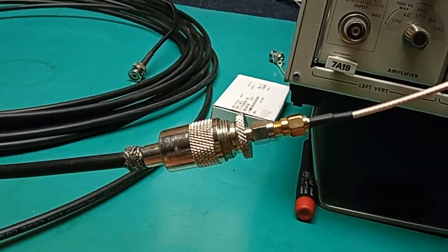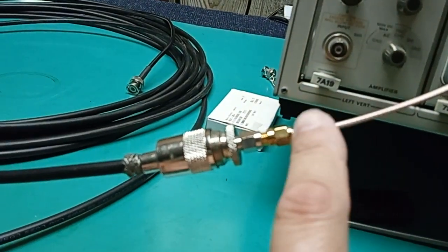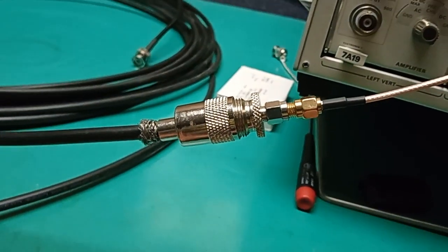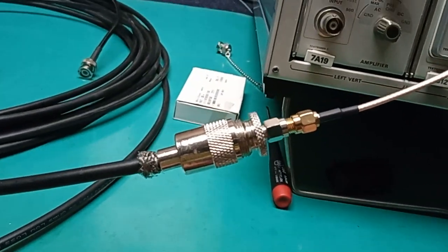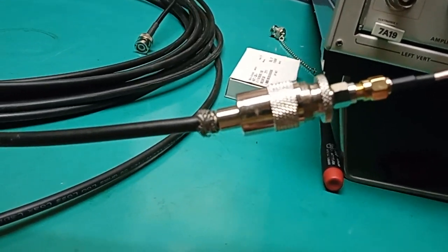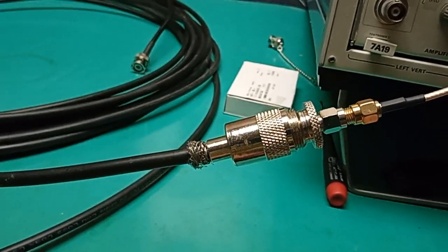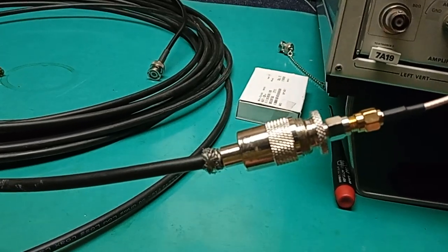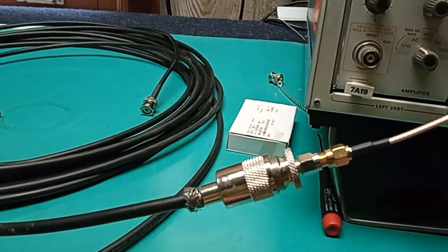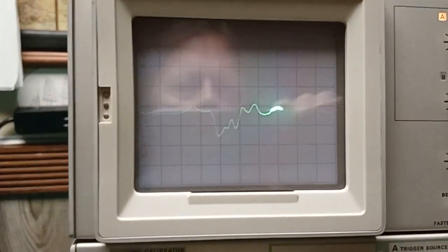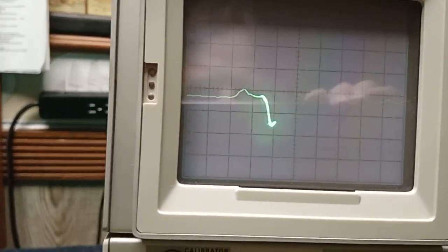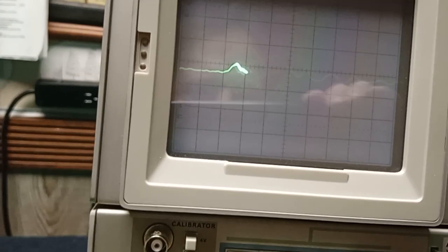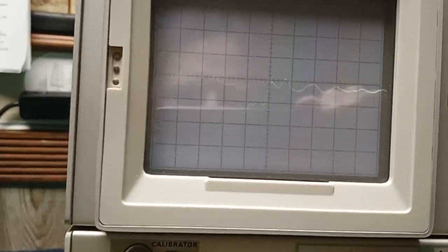Normally for any decent RF work, we'd use only the same kind of cable, with a minimum number of connectors, but this goes to show the horrible reflections in a typical amateur radio antenna system loaded with connectors and switches that do not show in the SWR meter. The SWR meter will not detect that. But that's reflected RF that an ALC can pick up and cut the gain of the transmitter back. And this kind of thing also results in RFI in the ham shack.